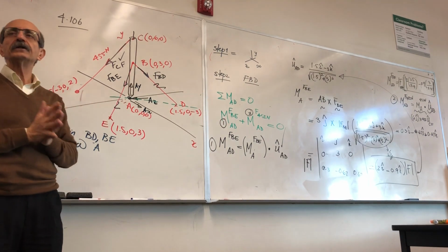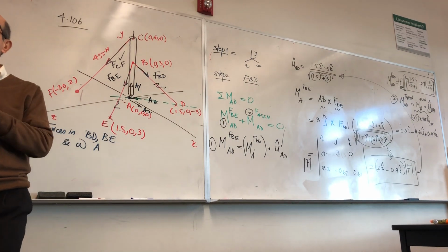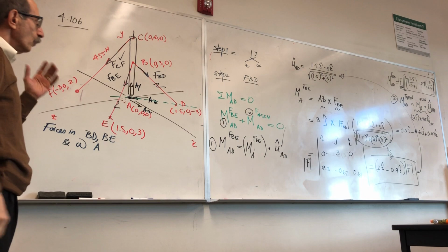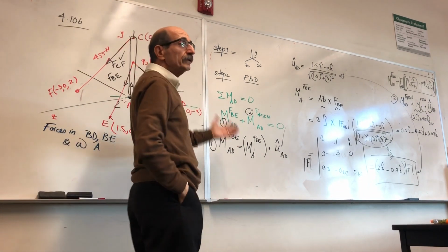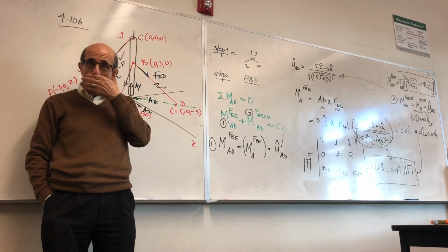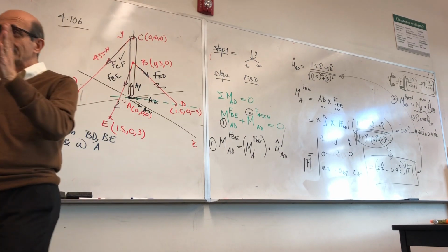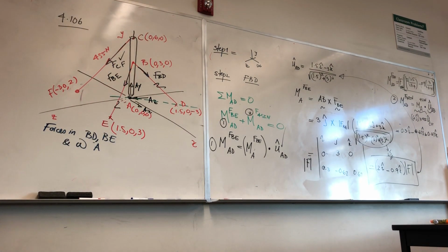The important thing is, though, remember the concept. What does summation of moments about an axis mean? Or what is the moment of the force about an axis? Which is going to be your next exam, by the way, right? Moment of the force about an axis, you find the moment about a point, and then the dot product of that and the unit vector of the axis. Yes? Well, this is going to be on the exam as well.